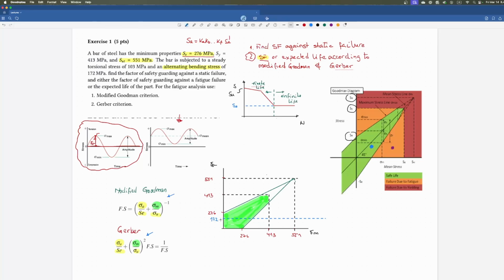Yeah. So the time I have taken here is because I'm just explaining how to do this stuff. But you don't need to draw this either. You can just look it up and use this Goodman diagram that you have here and overwrite things there. Then, which means that if my stress is somewhere around here, my mean stress is somewhere around here. So for sure, I need to use this one. Yeah. So again, the real challenge is determining the mean stress.